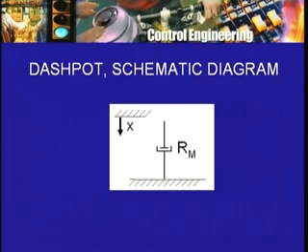But here is a practical dashpot, which you can think of really as a cylinder, not this one necessarily, but think of a cylinder with a piston at one end of it and with air under the piston, and assume that the piston moves in an airtight manner. Then obviously as the piston moves in, the air is getting compressed, so it offers some resistance to the movement of the piston. In place of the air, one may have oil, and one has to make some proper arrangement and so on.